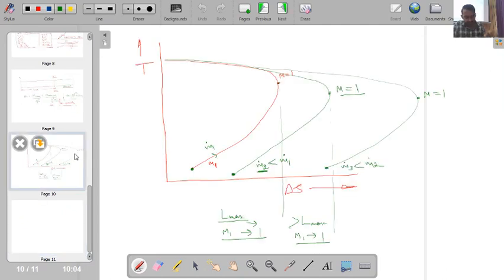So ultimately let me give you some physical idea. In case of supersonic flow, what happens? In case of subsonic flow, what happens? When molecules feel that some additional length is coming, they pass this information to the inlet, and they keep on modifying the inlet condition, they adjust the inlet condition. That is something which happens in case of subsonic flow situation.